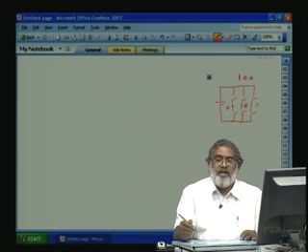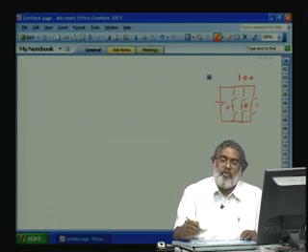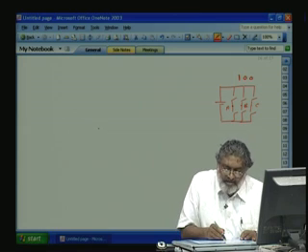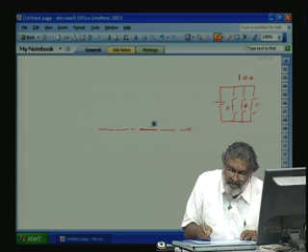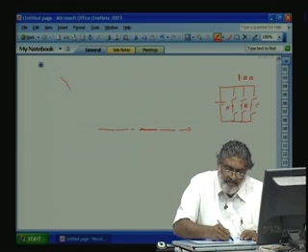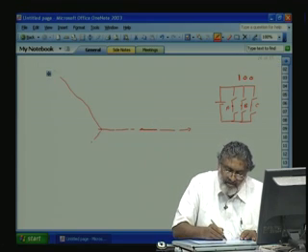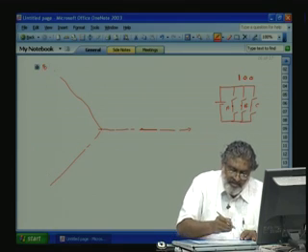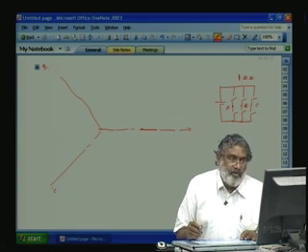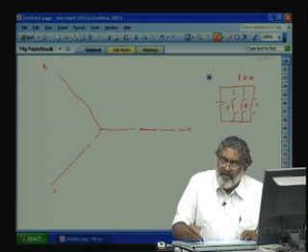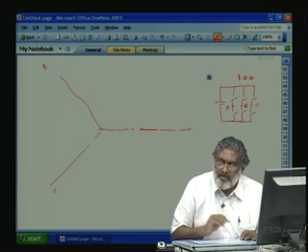Now, let us draw the combined effect of all the 3 phase pole voltages, that will give the vector. This is our A phase axis. A phase 120 degree phase shifted, we will get B, then we will have C. This is the B axis, this is C. When A leg is 1, 0, 0, A is connected to the top, B and C are to the bottom.